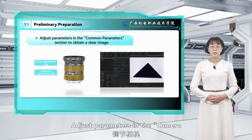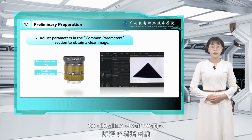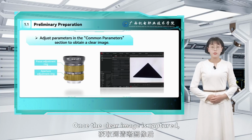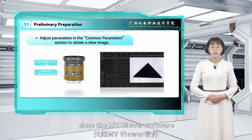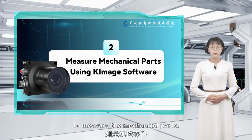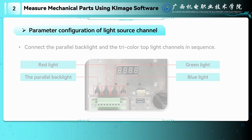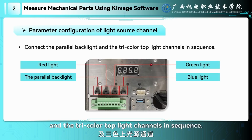Adjust parameters in the camera and common parameters section to obtain a clear image. Once the clear image is captured, close the NV Viewer software and open the KiMage software to measure the mechanical parts. First, set the light channel parameters. Connect the parallel backlight and the tricolor top light channels in sequence.